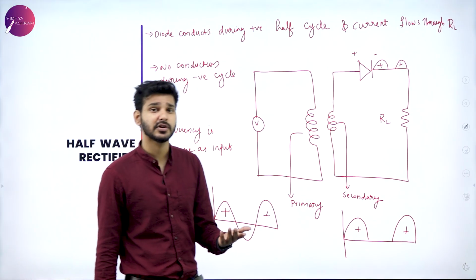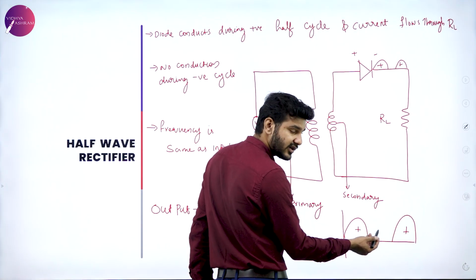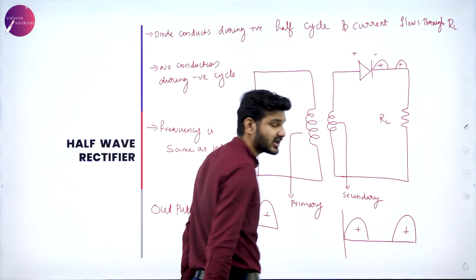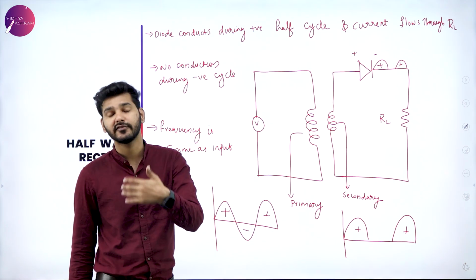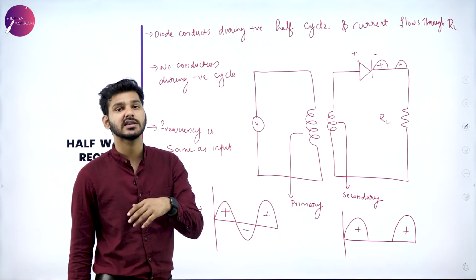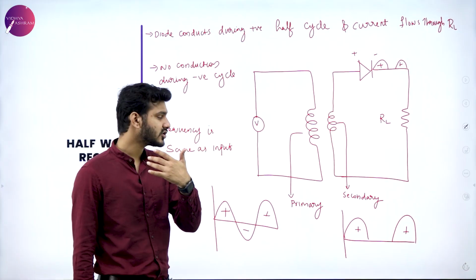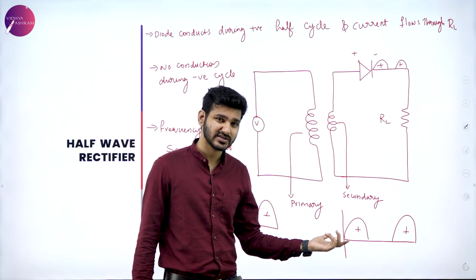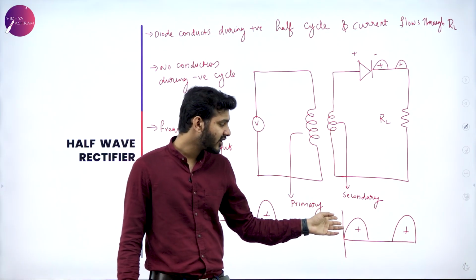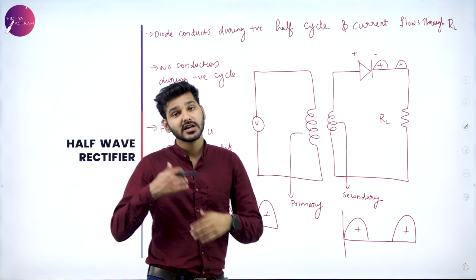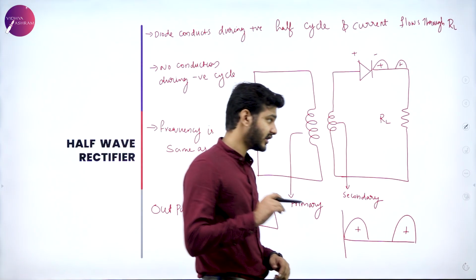The drawback of this particular rectifier is that if you convert this waveform, it is not actually one straight continuous line. It is a bumpy road. So it is not converting and giving you full DC. Half of the AC current is being wasted, which means the negative half is not being utilized. Since the negative half is removed and not let through, we are only getting this bumpy design. So because of that, we invented what is known as a full wave rectifier.